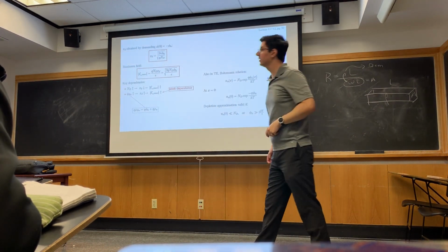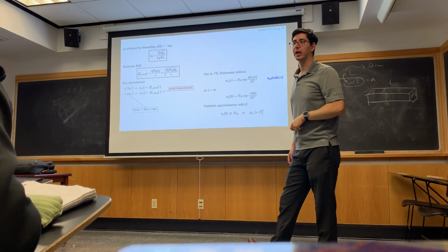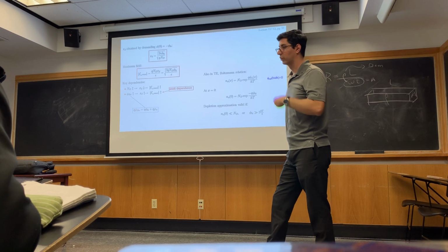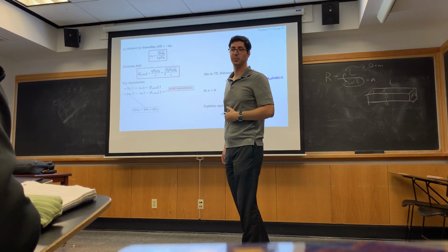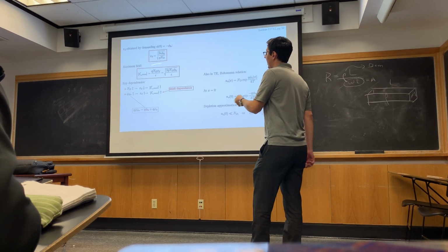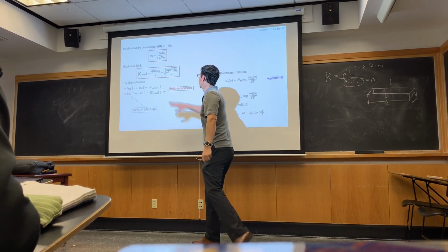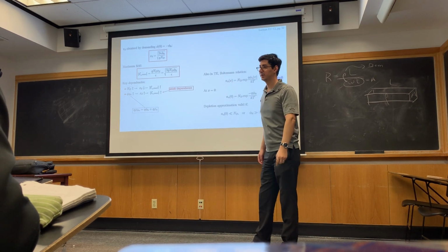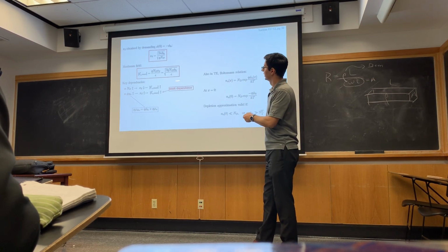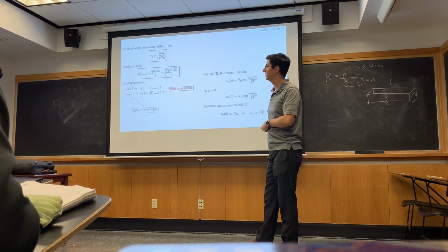This is the exact same solution that you had for an asymmetric PN diode, where one side was heavily doped, and ND would be the lightly doped side here. Okay? The maximum field has the exact same expression as for an abrupt PN diode, where ND again is the lightly doped side.